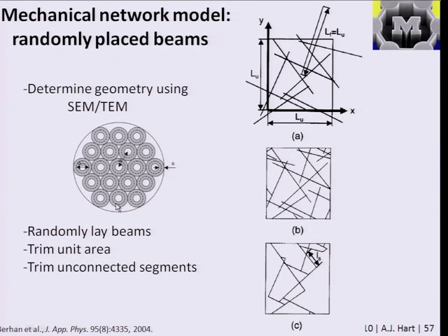So if we looked at a model of a mechanical network, we could consider it as an assembly of kind of randomly placed beams on a substrate. And we could reduce a network like this to a network where we only, say, identified the continuous load paths within the structure. Because now, we don't care about maybe there's semi-contact, there's close proximity. We're only going to transmit load through the places where the structures are actually hooked together. And then this could, for example, be related to a model of the structures that considers their individual stiffness and considers the stiffness and the characteristics of the joints.